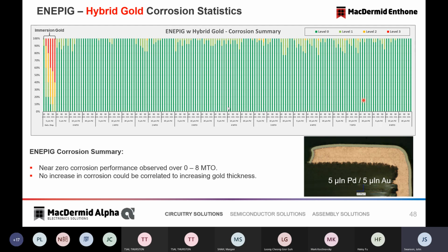Your name is Mark, yes? Yes. Mark, I can share with you, offline or another time, some interesting photographs of solder joints. As you build palladium thickness, you can find some palladium, and there's some reason to debate that higher palladium, once you get to what I would say are quite high, costly levels, can impose some problems. Not at industry standard levels, but as palladium thickness builds, that could be a consideration.